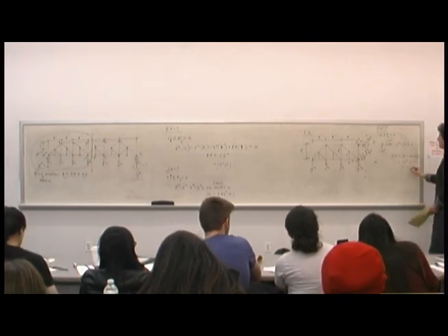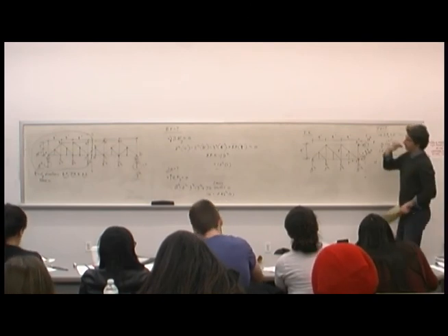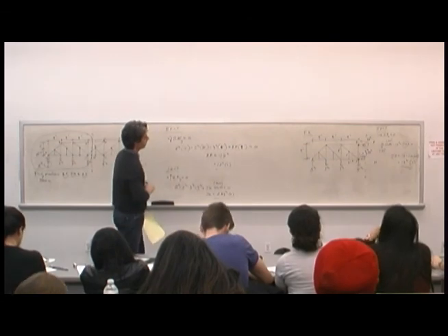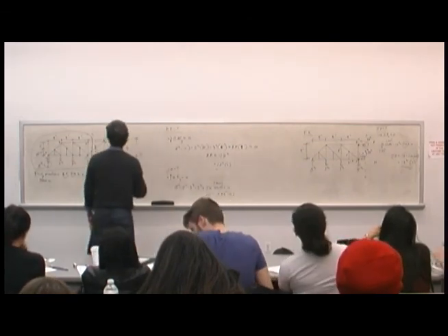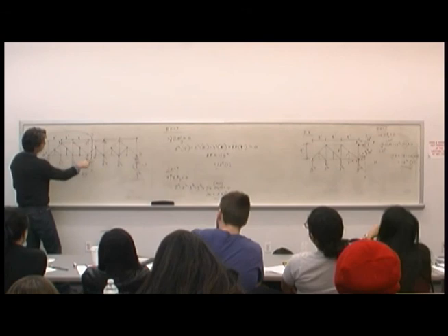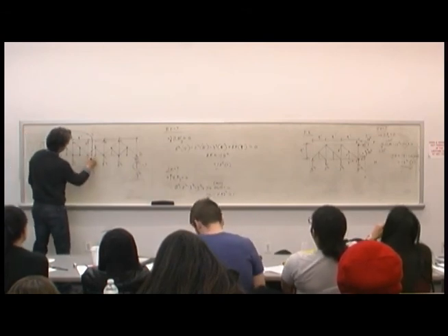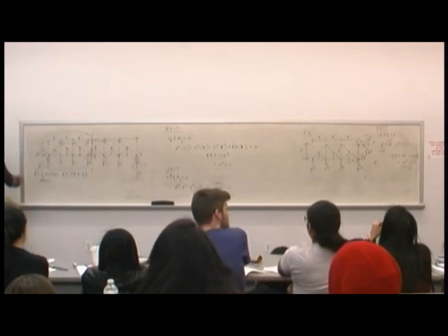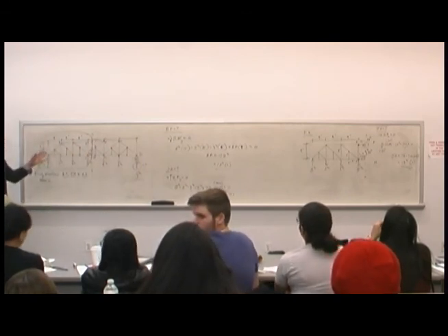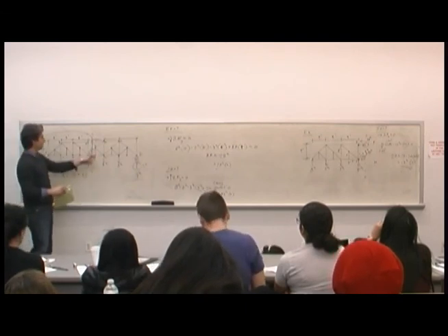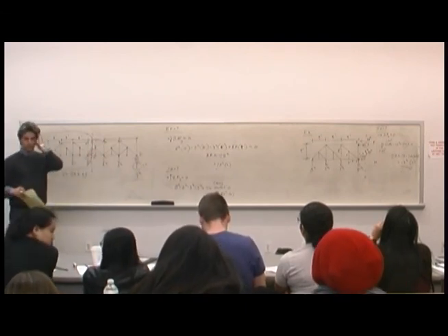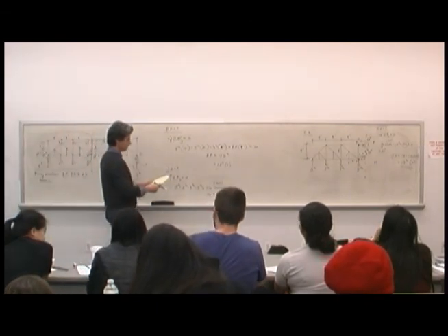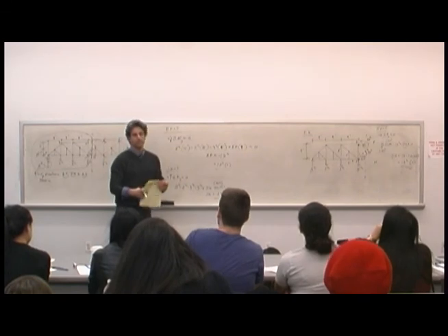Okay, so we solved for JH, we solved for our EF and JK. Right? So without going through all the joints, we were able to figure out what was happening here, here, and here. You can do that anywhere else. So if I gave you a problem in an exam for a truss, and I want you to look at one particular member, that's what you can do, right? You can figure out the force in that one particular member. So that's method of sections, right? So now you're experts in method of sections.